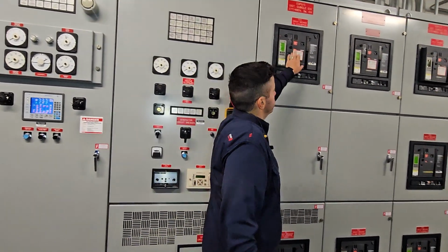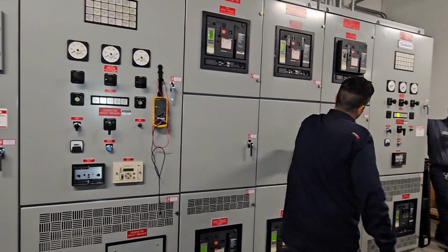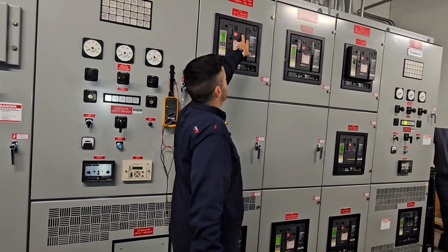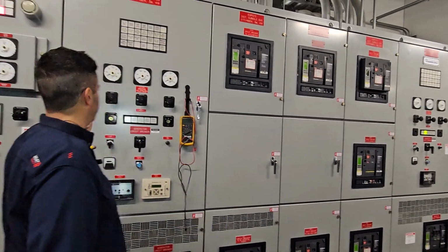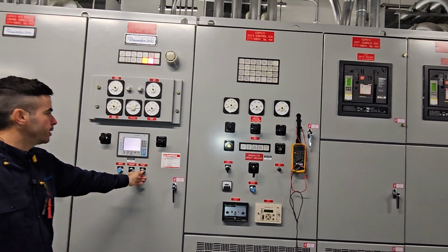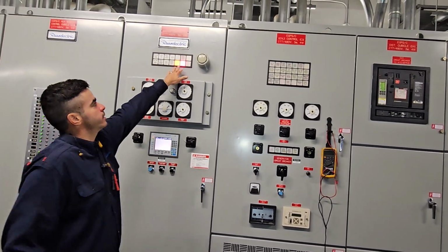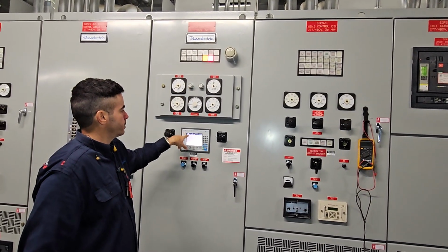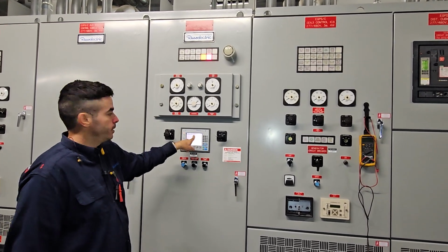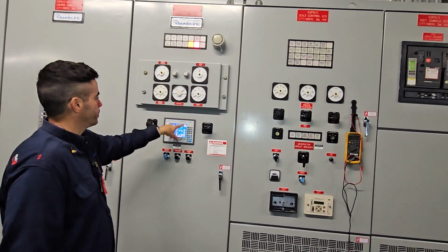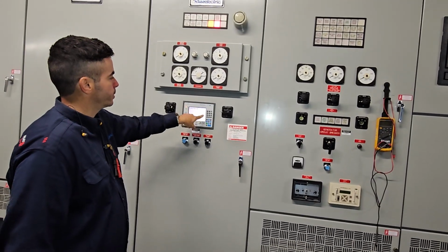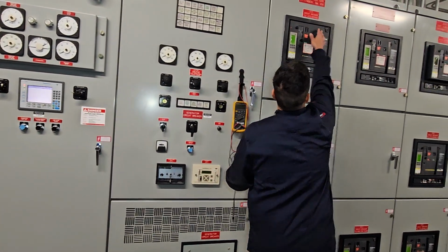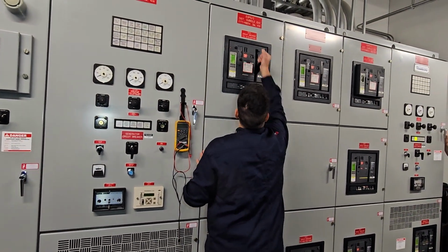These breakers are normally closed. So if there is a load connected, you'll see the breaker closed. If the breaker is not closed, you'll get an alarm, because that is not a normal condition. So you'll see this light over here, and that's telling you, hey, there is a problem. So you come down here and it says emergency feeder open. And then if you go to your one line, you can see that the status of the breaker changed to open. So basically you have to make sure that they're always closed.